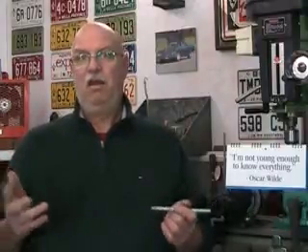Well, that block didn't have to be very dimensionally accurate. Its width was 2 inches plus or minus 2/1000ths of an inch. Not terribly accurate. But we did want that V right in the middle. So the block had to be square. Its outside surfaces had to be parallel as well. And we wanted that V within a thou in the center. But its dimensions weren't that crucial.